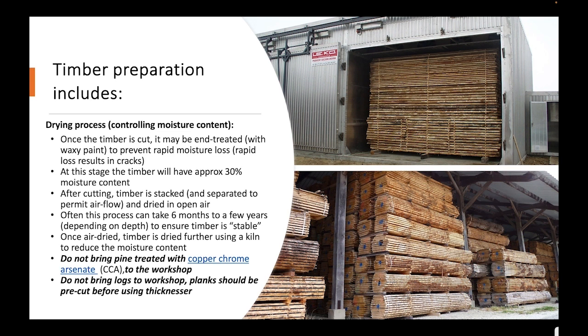After cutting, the timber is stacked and each plank is separated to ensure that there's plenty of airflow traveling through. The timber is stacked usually on a pallet that will be either lifted by some really heavy duty forklifts and trucks, but smaller timber yards will have smaller pallets. But it is important to note that stacked timber needs to be weighted properly. So you'll notice that on the image down the bottom here, all of the timber has been stacked really effectively. It's looked after, it's marked, so the consumer or the purchaser will know where it's come from, and it's a very clean way of dealing with the timber that's been processed.